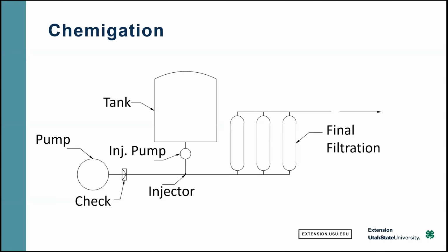And having a pump that has an interlock so that if you turn the system off, the pump doesn't keep pumping. That's important. Sometimes that's a pressure switch. Sometimes if you have a well on a pump, you'll have the electricity from the well and the injection pump tied together. So if that pump switch gets shut off, it kills the injection pump power too.